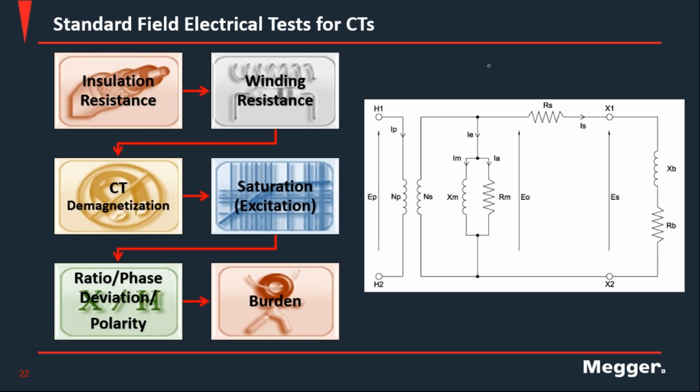The only thing is that in the sequence the customer mentioned, remember what I talked about in my previous question: you want to run a demagnetization in between or after those DC measurements, just to make sure that probable remnant flux in the core does not affect the subsequent test. So if you select your sequence manually, no issues, just make sure you run a DMAG after any DC measurement.